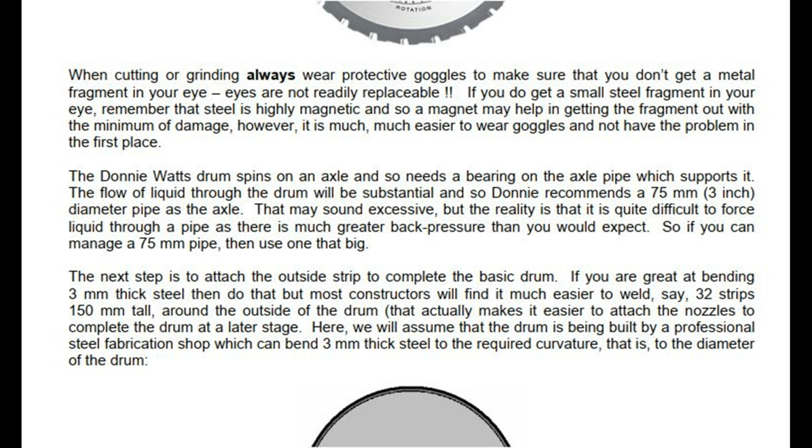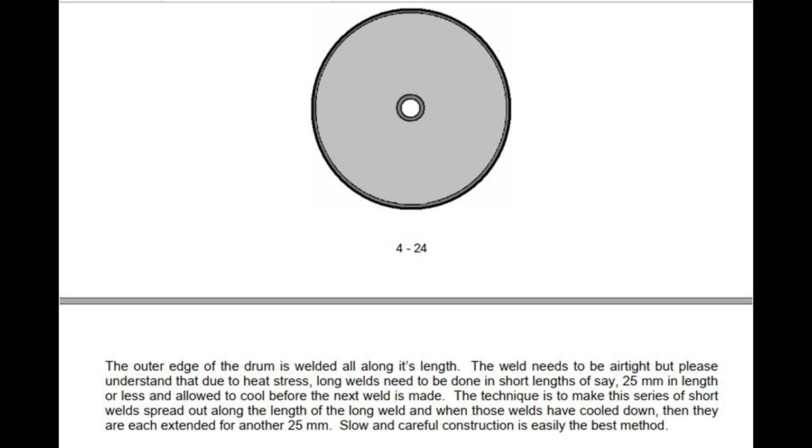Here, we will assume that the drum is being built by a professional steel fabrication shop which can bend 3 mm thick steel to the required curvature, that is, to the diameter of the drum. The outer edge of the drum is welded all along its length.